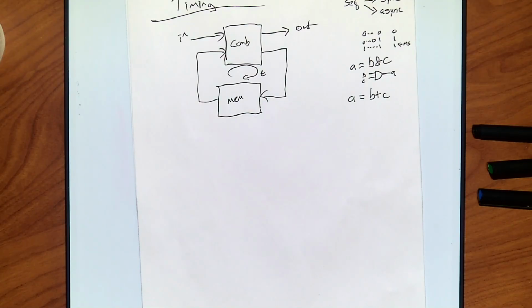So logical only checks two possible states. Bitwise does them all, so you're in essence building a whole bunch of gates when you do bitwise. Almost always we want bitwise when we're building hardware. Almost always you want logical when you're programming. That's why you probably only thought there was the double ampersand if you only dealt with C, C++, Java, whatever. They always do the double one. It's actually the other one that's built in, but it's almost never what you want because it's usually the condition in an if statement that you want true or false. So you almost always mean logical in those cases.